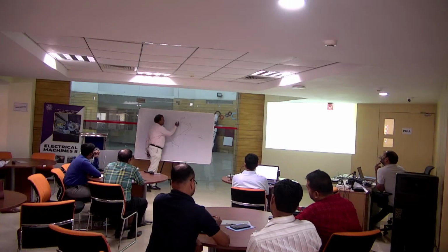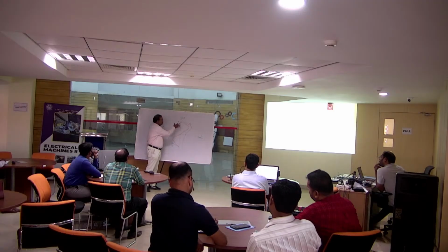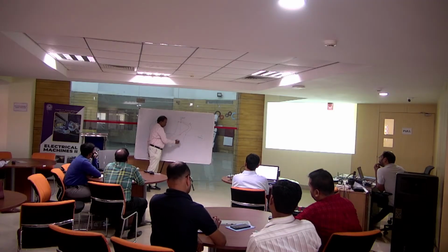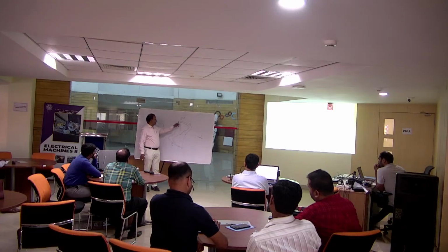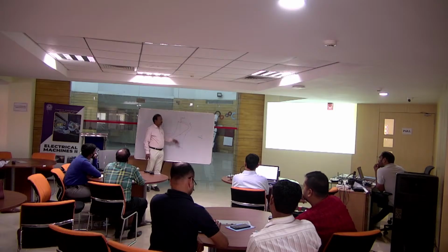So in this region, the speed and torque are in opposite directions, so you get braking action. Similarly also here. So this is what you operate here during dynamic braking.